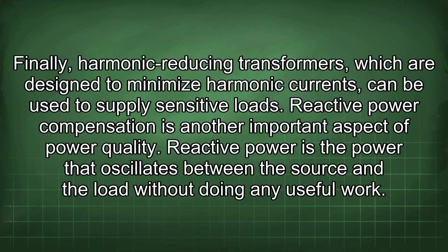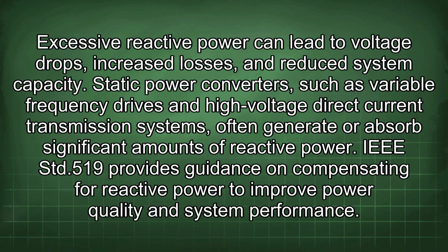Reactive power compensation is another important aspect of power quality. Reactive power is the power that oscillates between the source and the load without doing any useful work. Excessive reactive power can lead to voltage drops, increased losses, and reduced system capacity. Static power converters, such as variable frequency drives and high voltage direct current transmission systems, often generate or absorb significant amounts of reactive power. IEEE Std.519 provides guidance on compensating for reactive power to improve power quality and system performance.